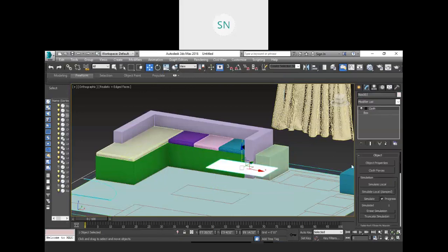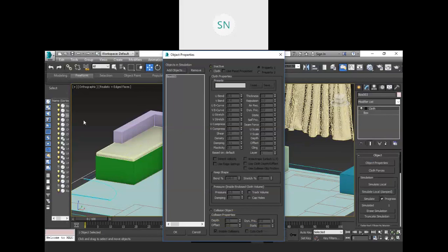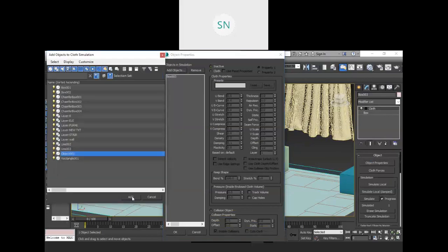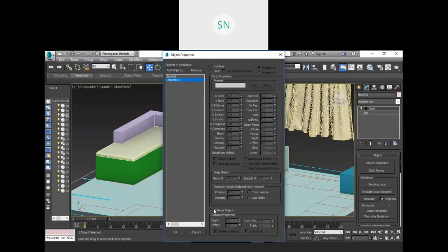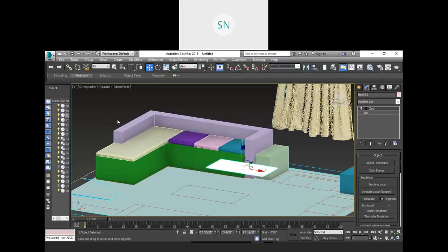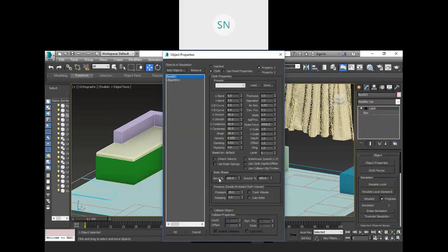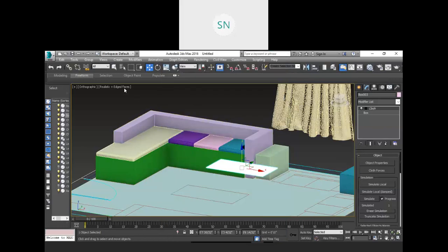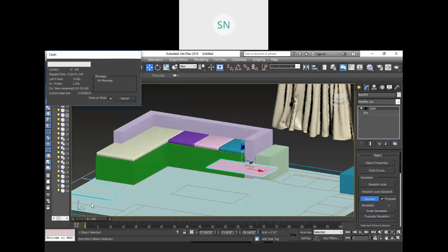Okay, so click on add object 1, add, and object 1 is my collision, and this box is cloth with some pressure. So provide your pressure over here, hit OK, deselect everything, select it again and check it again, cloth and pressure, and this should be collision. Okay, now click on the simulate, so it will blow like a balloon, right?